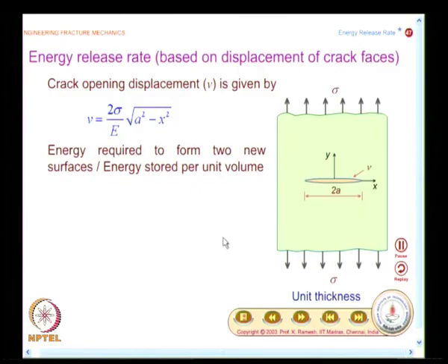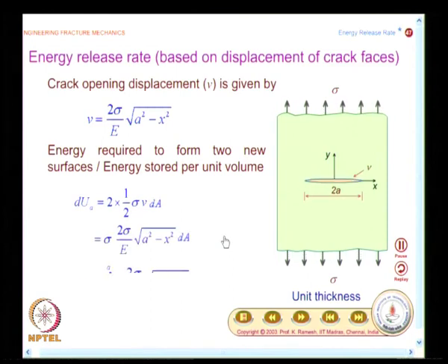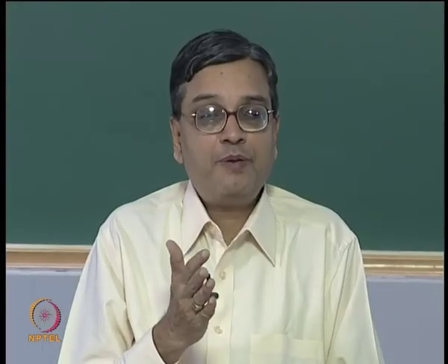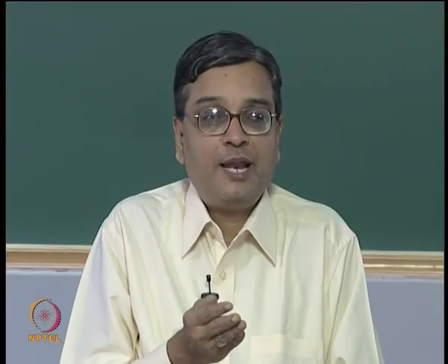Your question also borders on why we use a biaxial loading situation for a uniaxial loading situation. This representation comes mainly because at the time when these theories were developed, people were looking at a hole in a tension strip, an elliptical hole in a tension strip, and Griffith also developed his fracture strength based on uniaxial loading.